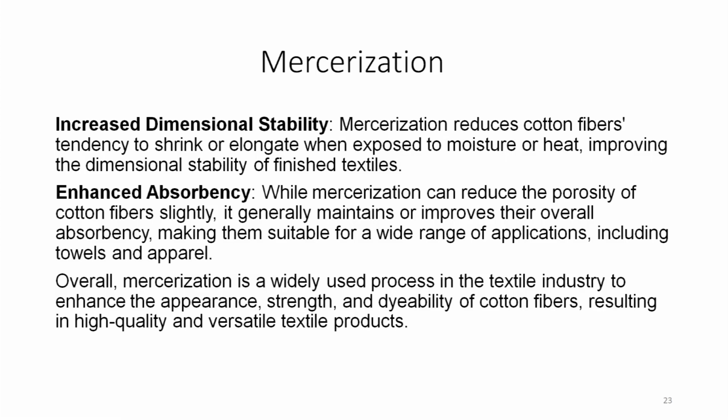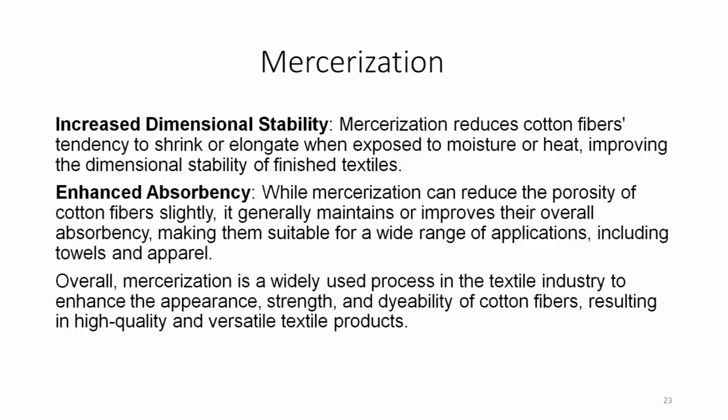It also gives increased dimensional stability. Mercerization reduces cotton fibers' tendency to shrink or elongate when exposed to moisture or heat, improving the dimensional stability of finished textile. So, mercerization has many facets and many advantages that it adds to the cotton. Enhanced absorbency.